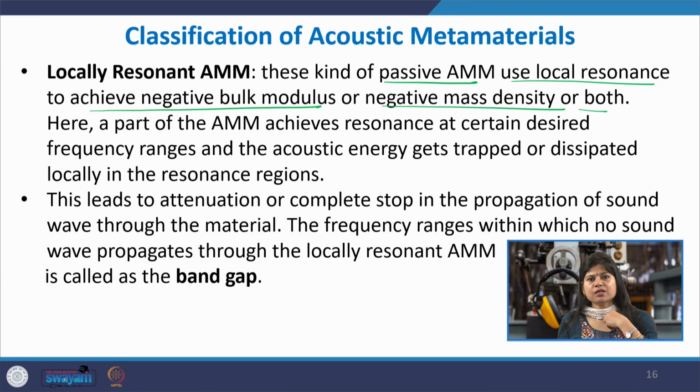So in the same way, in the case of metamaterials also, suppose at a certain incident frequency some unit cells are set into resonance, what will happen? The sound waves that are getting incident on that particular region which is set into resonance, those elements will start to vibrate at a very high frequency. So all the sound energy that is incident in the part where the fundamental frequency matches with the incident frequency, the sound energy gets used up in driving that element in resonance, okay, and that is how the energy gets trapped or dissipated locally in those regions where resonance is observed or set, okay.